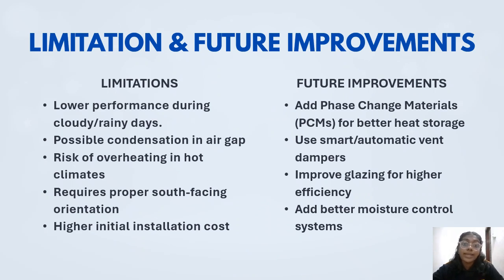Although the system has many advantages, there are still some limitations. The performance decreases during cloudy or rainy days because the system depends on solar radiation. There is also a possibility of condensation forming inside the air gap, which may affect efficiency. In hot climates, overheating can occur if proper ventilation is not maintained. Additionally, the system requires proper south-facing orientation for maximum solar gain, and the initial installation cost can be relatively high.